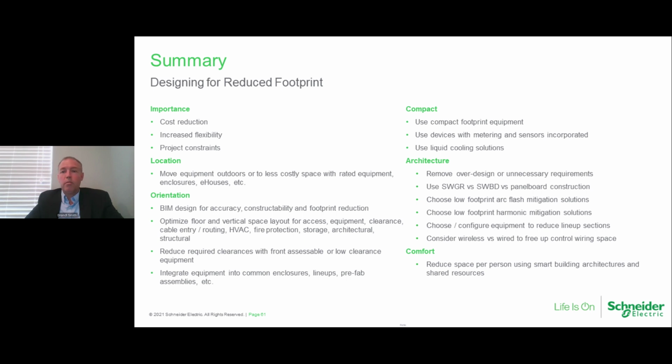The moving the equipment out, we do that all the time with NEMA 3R equipment, but we can also get creative. We can use an e-house and move equipment that wouldn't traditionally be moved out and move the entire electrical room outside of the building.